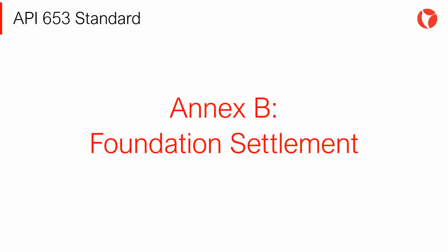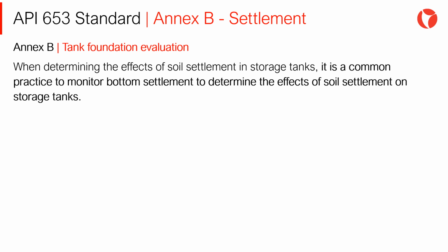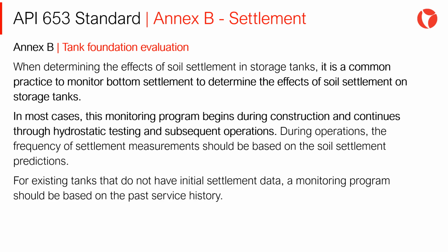Let's now review Annex B, Foundation Settlement. When determining the effects of soil settlement in storage tanks, it is a common practice to monitor bottom settlement to determine the effects of the soil on the settlement of storage tanks. In most cases, this monitoring program begins during construction and continues through hydrostatic testing and subsequent operations. During operations, the frequency of settlement measurements should be based on the soil settlement predictions.